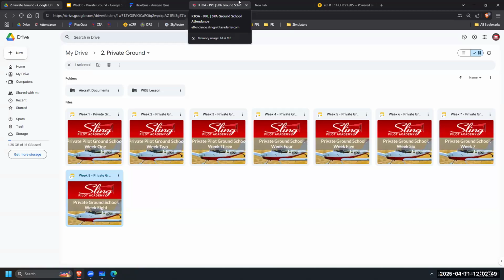Because of the resistance, the plane wants to roll because of the propeller swinging it. It's a big force, right? Even though it's only 100 horsepower, the propeller is swinging that way, so the plane wants to roll in that direction. Correct? Can it roll on the ground? Hopefully not. So what happens is the left tire feels a lot of pressure now. All right, that was one.